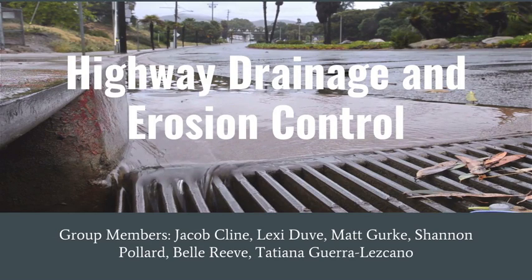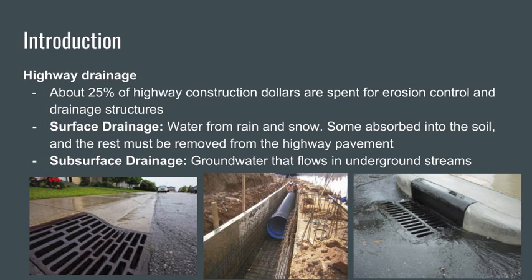In today's video, we're going to talk about highway drainage and erosion control. In this topic, we're going to talk about highway drainage. About 25% of highway construction dollars are spent for erosion control and drainage structures. The two topics for highway drainage are surface drainage and subsurface drainage. Surface drainage includes water from rain and snow. Some is absorbed into the soil and the rest must be removed from the highway pavement. Subsurface drainage is groundwater that flows underground.